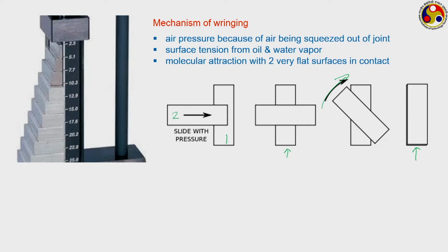One big problem with the use of gauge blocks is that, being made of metal, they suffer from the problem of thermal expansion. As the temperature changes, their length can change, and therefore they can give an accurate reading only at the temperature at which they have been calibrated or fabricated. So maintaining the temperature is extremely important while using the gauge blocks.